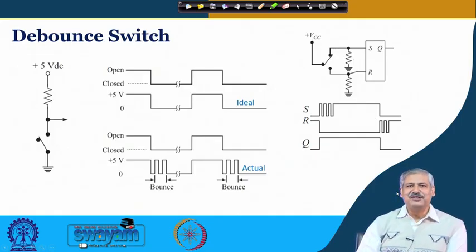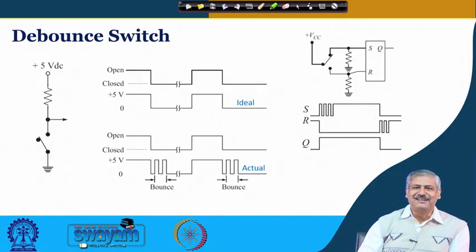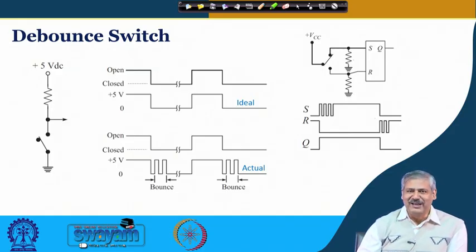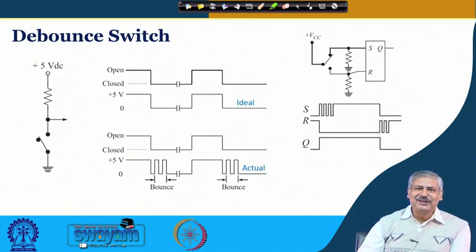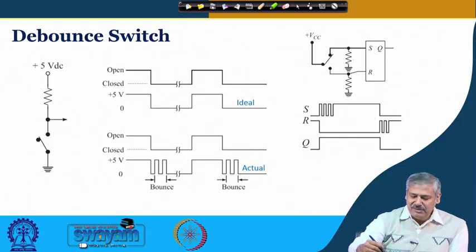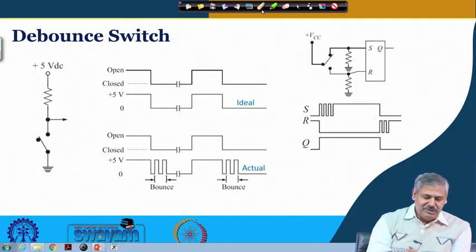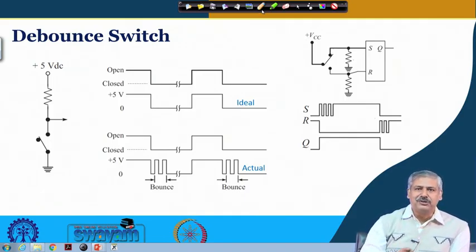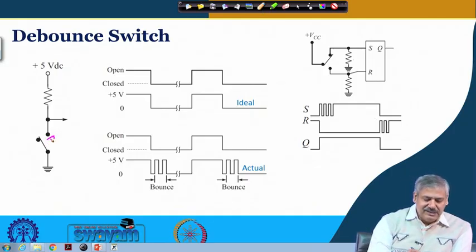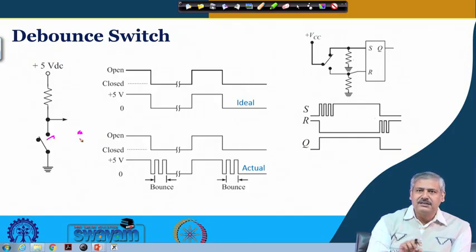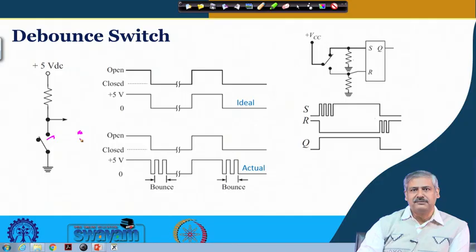Now, there will be many applications we shall see later, and complex sequential logic circuits will be made. Right now we can see one application where a debounce switch can be made using an SR latch. Okay. So what do we mean by a debounce switch? When we are connecting a mechanical switch which has a spring-loaded kind of thing, whenever it is getting connected here, it will make a connection, disconnection, connection, disconnection, connection, and then it will settle. So there will be a small vibration, right.